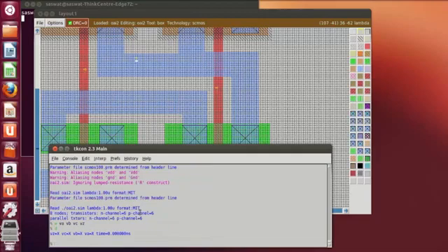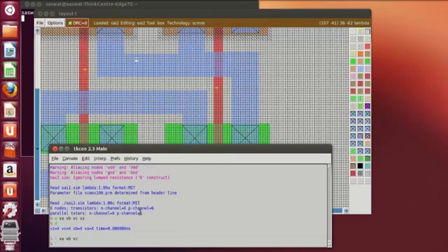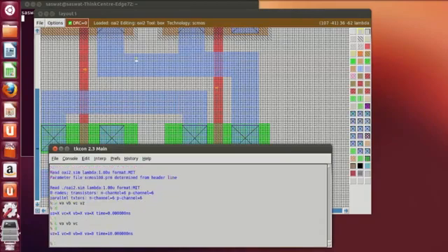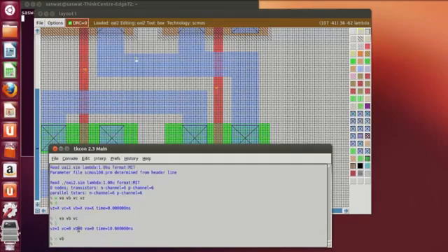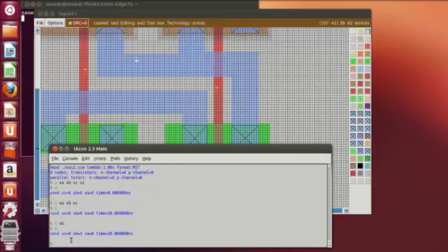And all have the X value. Then if I give low value to VA, VB and VC, what will be my output? If these two are 0, 0, the OR output will be 0. These two are 0, then again the AND output will be 0. Then the final output will be the invert of 0, that is 1. See, VZ is 1. If I give high value to VB, then what will happen? These two are ORed, that is 1. 1 and 0 is 0, the invert is again 1.